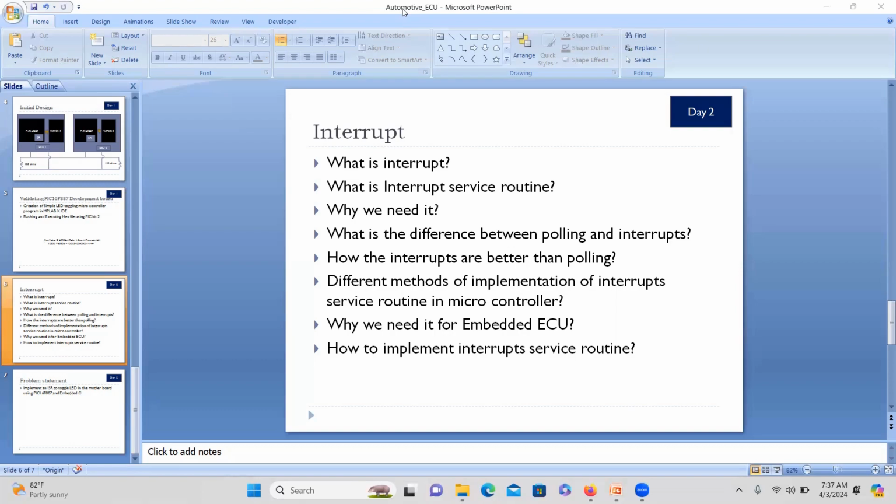You have to push your current program counter value to the stack, and then push all the intermediary values that you have in your main program to the stack memory before you go to that task. Because if you simply leave them and go to service something else, when you come back you need those data, right? Those intermediary values are needed. So even when we use interrupts, we cannot simply jump from here to there, do the things and then come back.